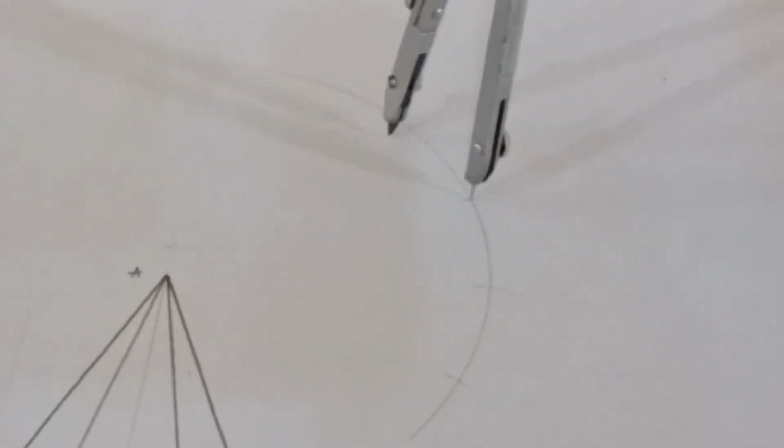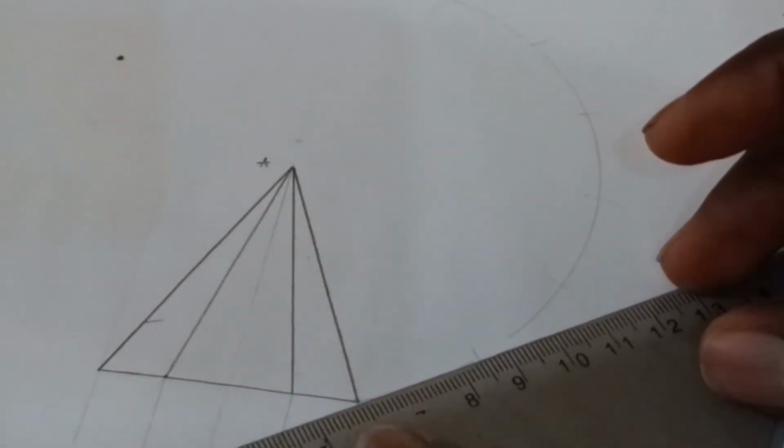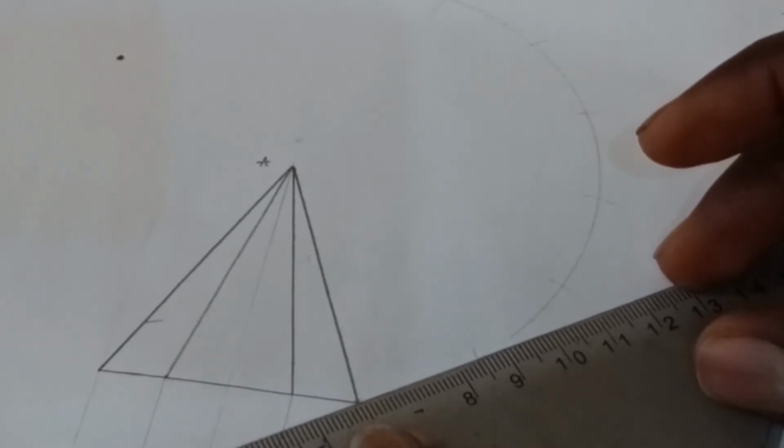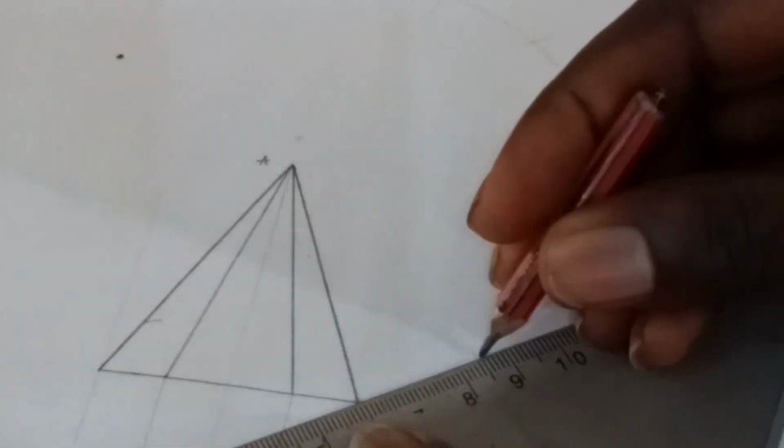Right, so the new arc you're cutting is the new midpoint. Nice and easy. Make sure you don't alter the radius, please, because if you alter the radius, it will alter the dimension being transferred. It's pretty much 2.5. Make sure you cut 6 arcs before stopping, and don't alter it. And this also has to be done with thin lines, because it's still a construction we're doing.